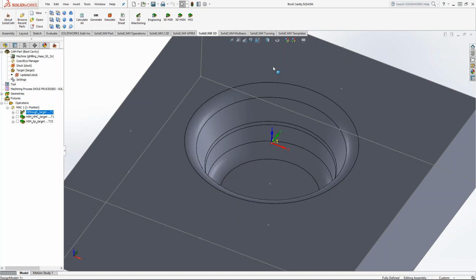This particular mold, and most of the molds that I did, cavities and cores, I did a few out of aluminum prototype tools, but most of them were P20 or a 17-4 precipitation hardened stainless, some H13, maybe an S7.